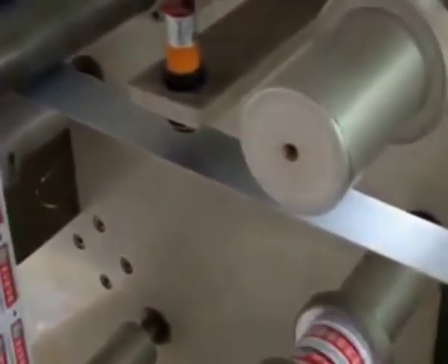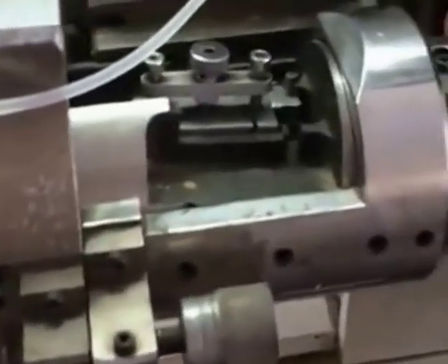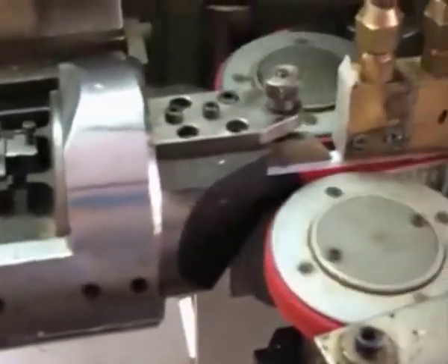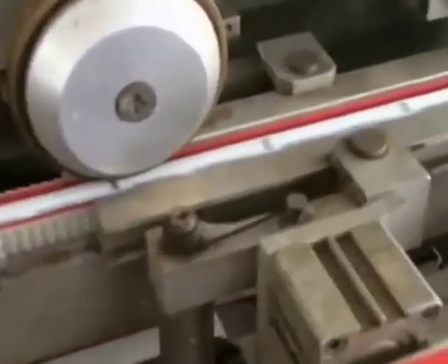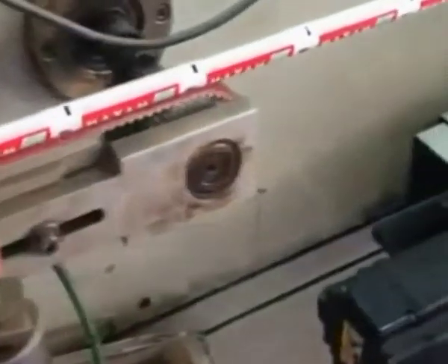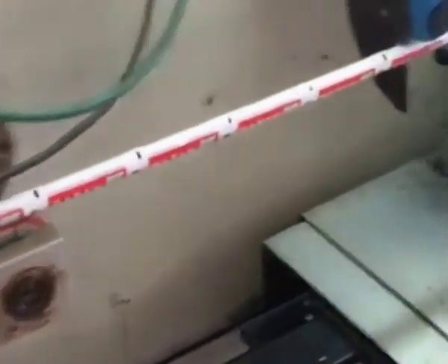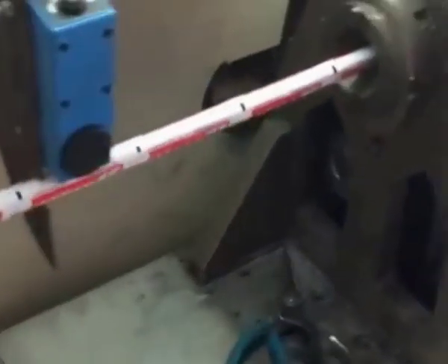B. The formed tubes then pass to a trimming machine where they are cut to length, a thread is cut or rolled down the nozzle, and the face of the nozzle orifice is cleaned. The shoulder, which is relatively rigid, may be decorated, for example with concentric rings, if required. The tubes are then ready for the finishing operations of internal coating, enameling, printing, and capping.